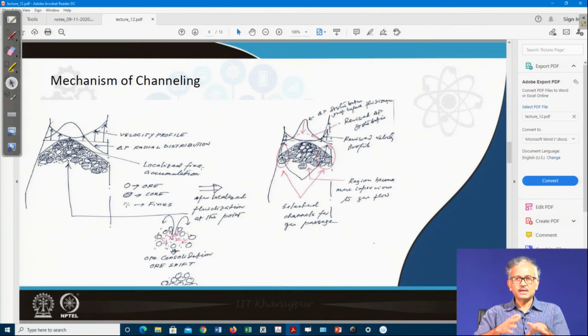Another corrective action for the pressure drop, and the most important one, is the top pressure. If you find the local pressure is increasing, you can increase the top pressure. What is the top pressure? That is the pressure at the top, which you can increase. If you increase the pressure at the top, what will happen? With the bottom pressure remaining constant, if you increase the top pressure, the overall pressure drop will decrease. So, you can increase the top pressure such that the pressure drop in the furnace decreases. The overall pressure drop will decrease, and the local pressure drop also decreases. So, that is the way.